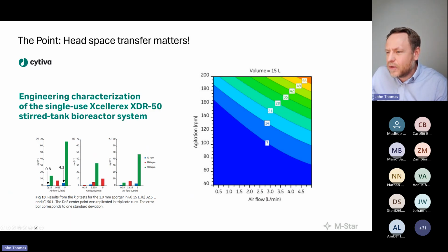We see that as our gas flow rate goes from 0.25 to 5, that's going up a factor of 20 times as much gas, and no breakup. Bear in mind, it's just kind of like bubbles rising, just in an airlift system. No meaningful breakup or coalescence, not enough energy to do it. Our measured KLa only goes up by a factor of like 4.5. Like, that's weird. And people are like, oh, well, the bubbles are breaking up.